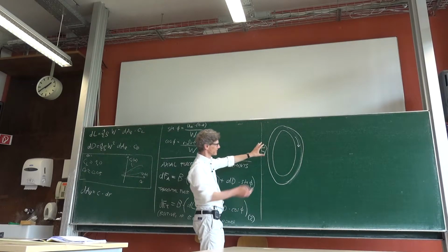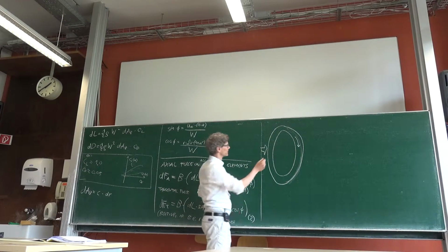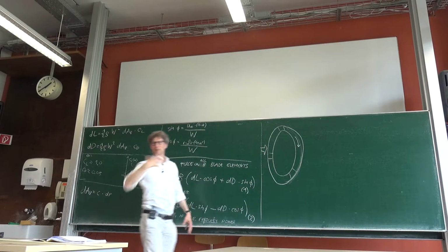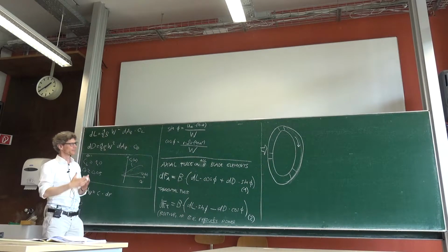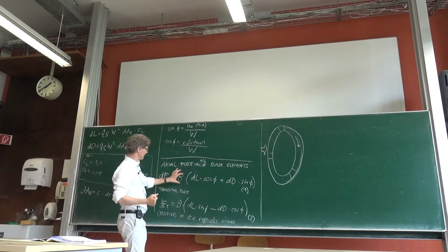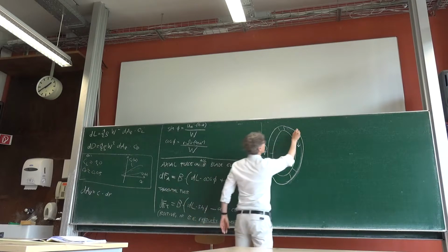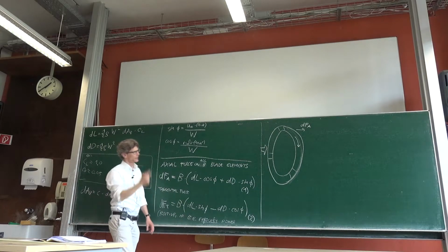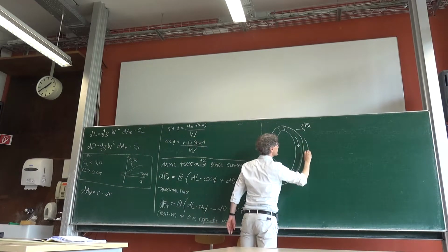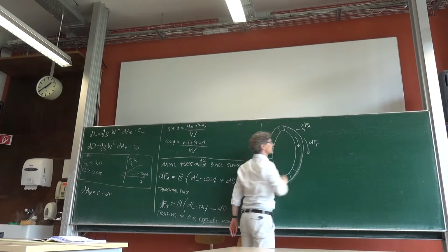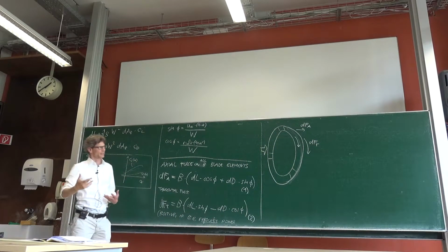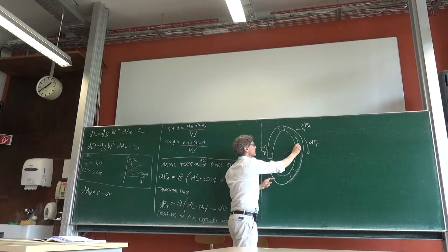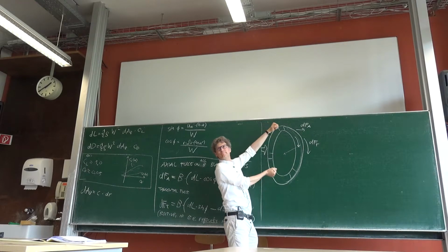So what I just said is on this annulus, for example my 3 blades, I collected already the total force that these 3 blades experience. So this is dFA, the force in this direction. And then the force in the tangential direction is here. And because in reality it's an annulus, I could also multiply this with the length of our radius if I like, and then I would get a torque.